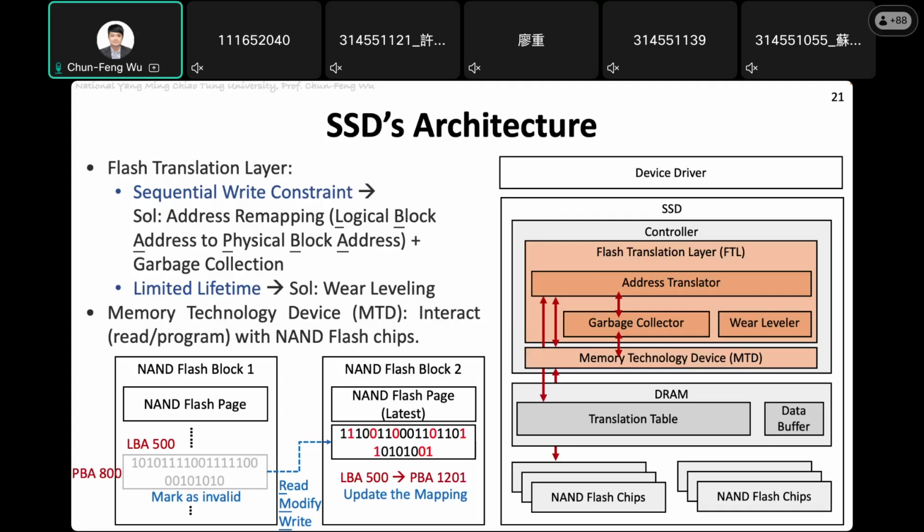But the rest of the pages in the block, maybe they are super healthy because the SSD only accesses that page. So in wear leveling, the SSD will control and distribute all the accesses to all the cells to absorb all the wear. So the SSD cells will become worn out at a very close time. Then it can extend the lifetime.